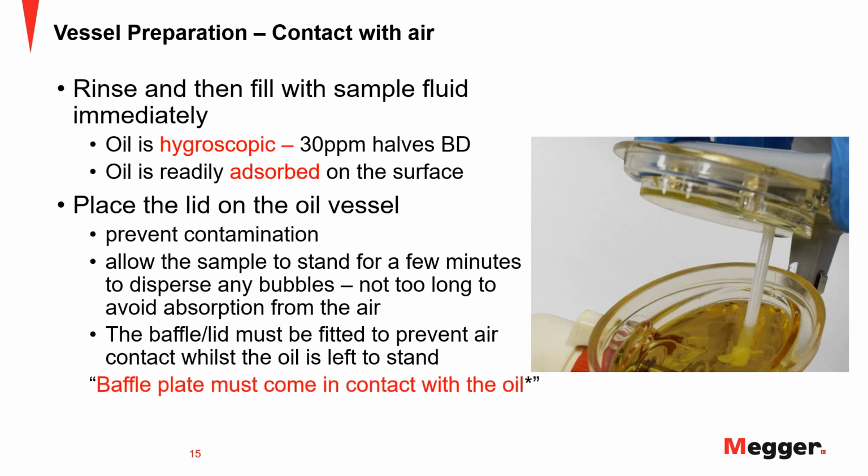And a very important note here is that the baffle plate must come in contact with the oil. So if you fill the oil to the fill line, which is the 400 ml fill line, you then place the baffle plate. It actually sits just on top of the oil. So again, it's minimizing any contact with air that may exist in the headspace. And we also need to ensure that the oil doesn't pass the upper surface of the baffle plate. And this will happen if you fill above the fill line. So make sure you fill your oil to the fill line, and then that will not cause this escape of oil through the top of the vessel. Okay, so that's contact with air.